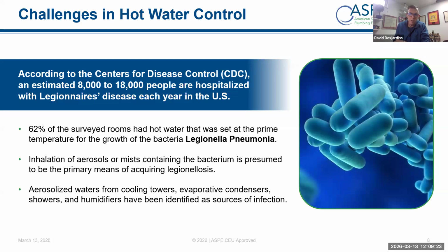But what happens is if we bring that into a man-made water system at the right temperatures and in stagnant conditions, that's where it starts to amplify. Now, I could have a glass of water laced with this, and I could drink it, and have no issues, right? It's a respiratory disease, so it has to be aerosolized, and I breathe that in.